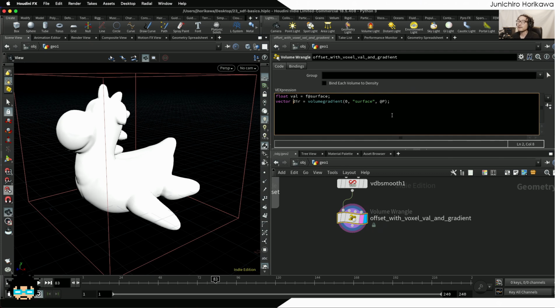So let's see how I can do that. To do that, I'm first going to create one vector value named, let's say, dir xz, since the planar direction is the xz plane, and copy the gradient direction right here. The first thing I would like to do is set the y value for this to 0 so that it becomes a 2D vector value. After that, I'm going to normalize this so that the length of this vector becomes 1.